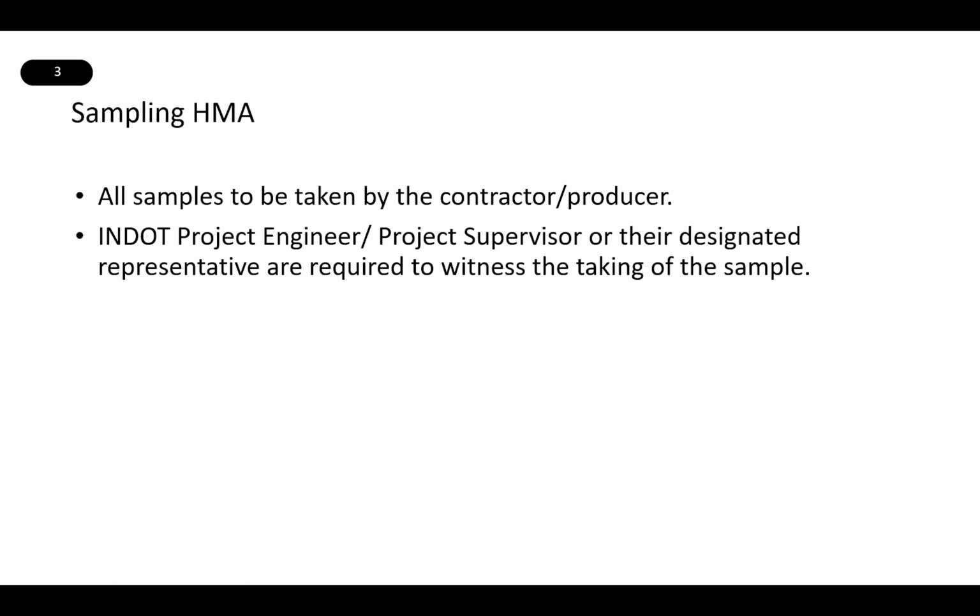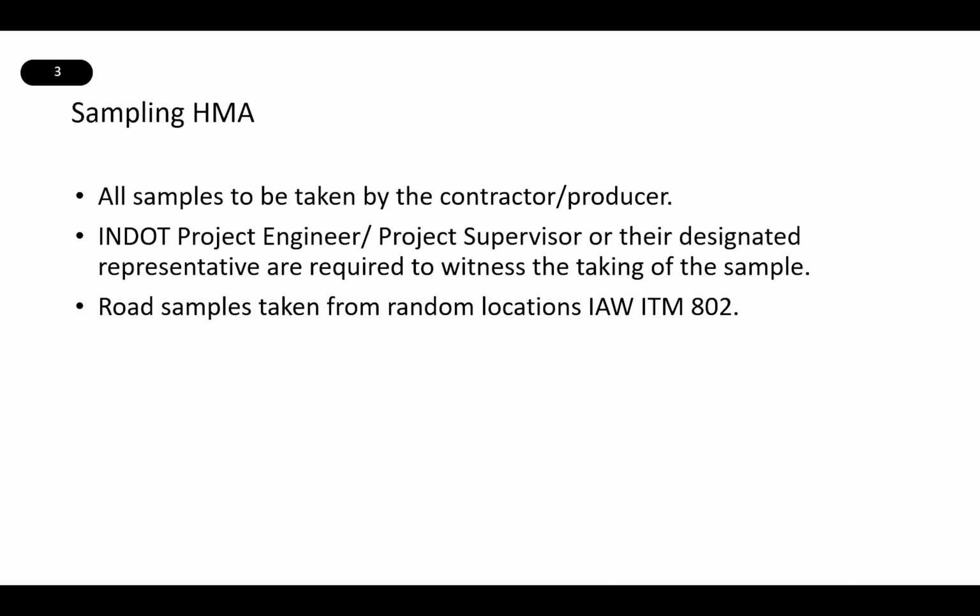Sampling HMA. All samples are to be taken by the contractor/producer. INDOT does not take the samples. They are required to witness the taking of these samples. Samples are taken from random locations in accordance with ITM 802. They are determined by random number generators or tables within the ITM.